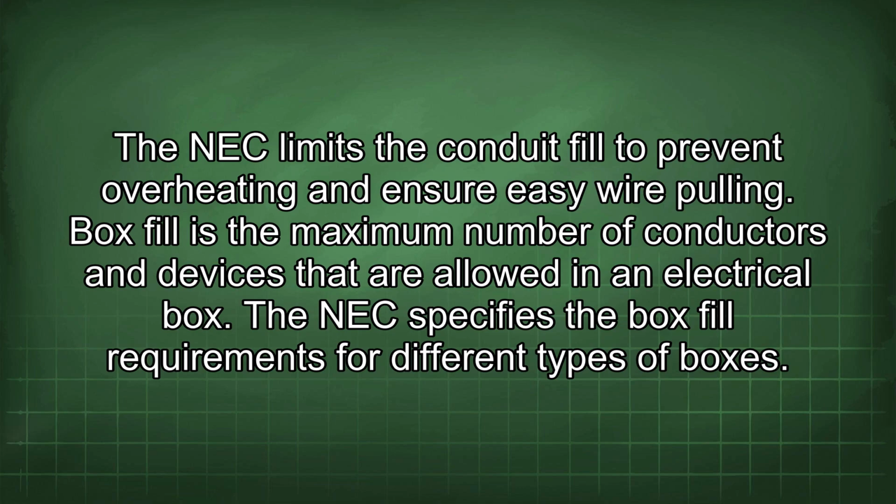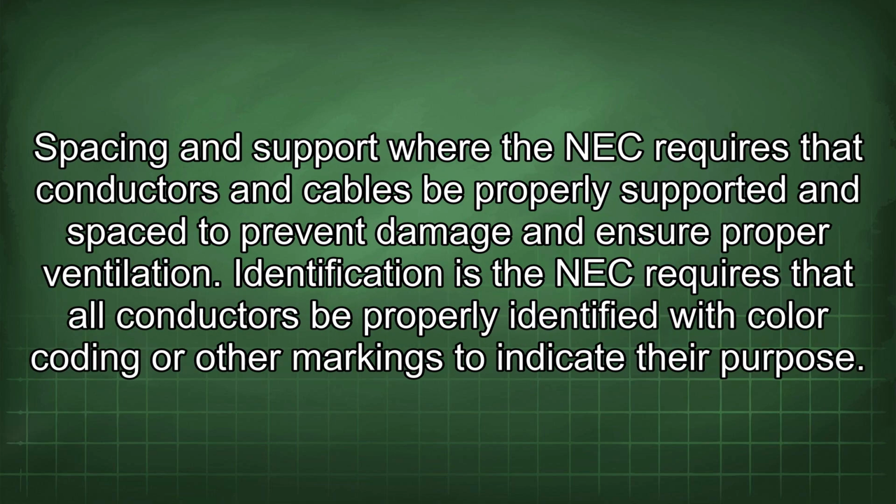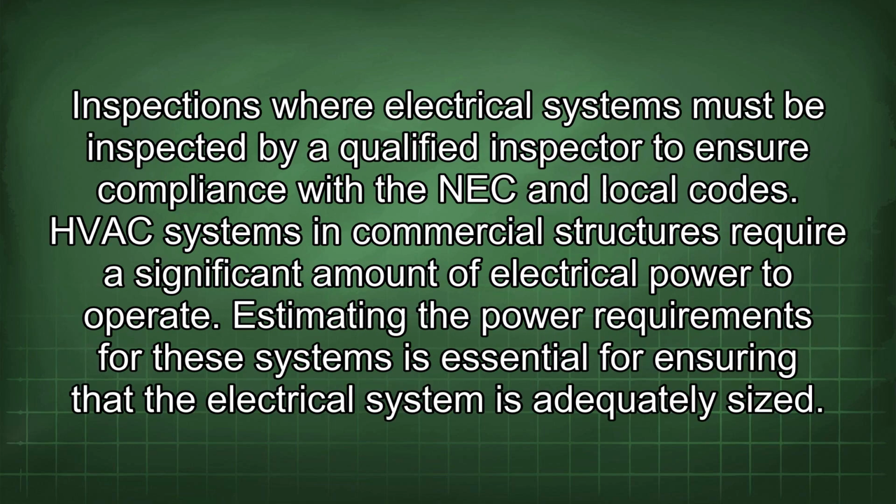Box fill is the maximum number of conductors and devices that are allowed in an electrical box. The NEC specifies the box fill requirements for different types of boxes. Spacing and support, where the NEC requires that conductors and cables be properly supported and spaced to prevent damage and ensure proper ventilation. Identification, where the NEC requires that all conductors be properly identified with color coding or other markings to indicate their purpose. Inspections, where electrical systems must be inspected by a qualified inspector to ensure compliance with the